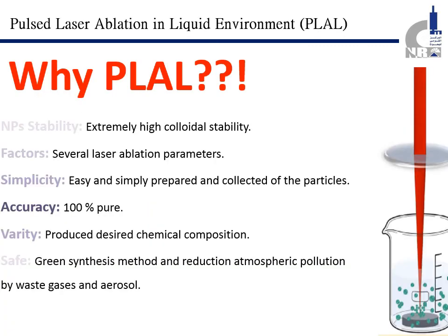So what is the difference in this technique compared with others? Nanoparticle stability. We can produce nanoparticles with high stability without using any surfactant. That is because the produced nanoparticle has a charge on its surrounding surface, which prevents agglomeration.